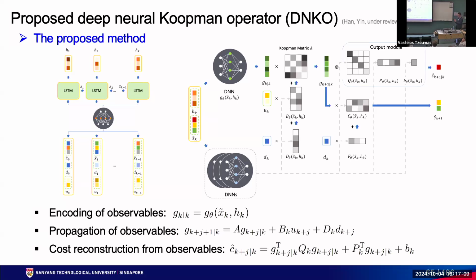For this plant, the temperature in one of the columns will be very high to facilitate the desorption of the CO2 from the solvent, but the temperature should not be too high. It should always stay below 145 degrees Celsius. My apology for not being able to convert it into Fahrenheit. But 145 is the hard constraint, so we will need to impose constraints on our MPC scheme.